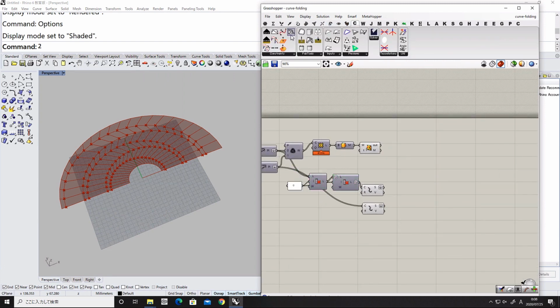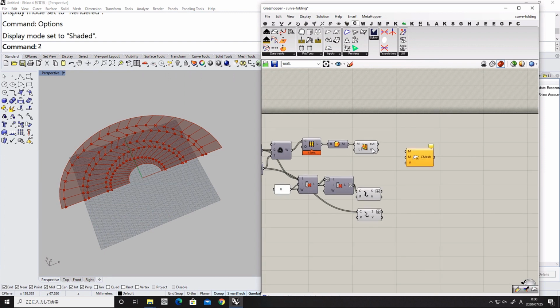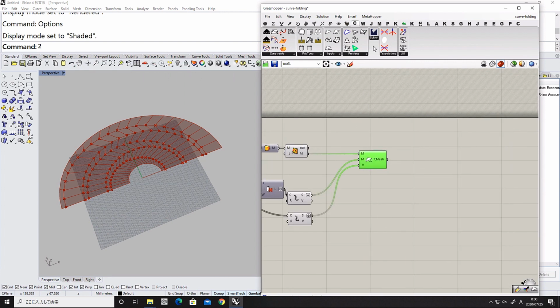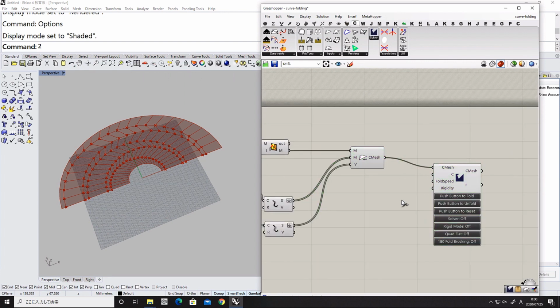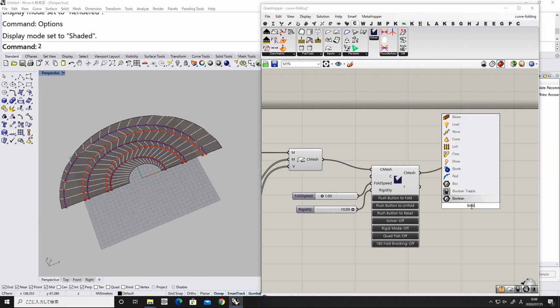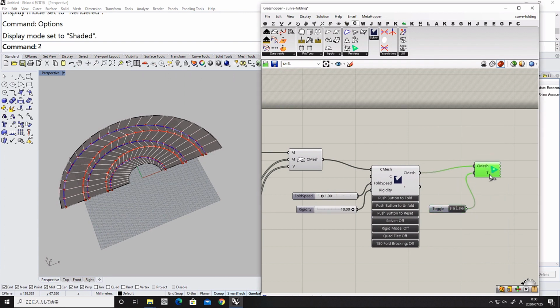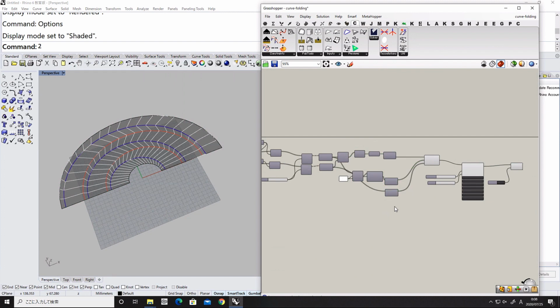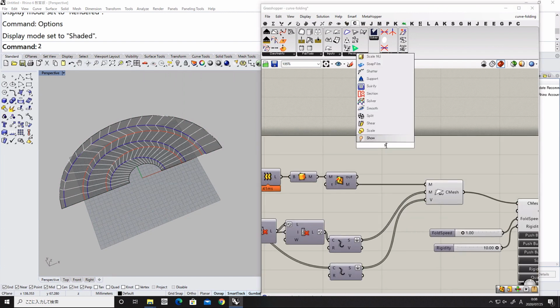And now is the time to create a mesh for the plugin called Crane, the specific geometry for Crane, in order to do the origami simulations, folding simulations. Okay, so first I have created a Crane mesh. I am going to set the fold speed and the rigidity, and then visualize the simulated mesh with the visual component. As you can see, the mesh is drawn in black.